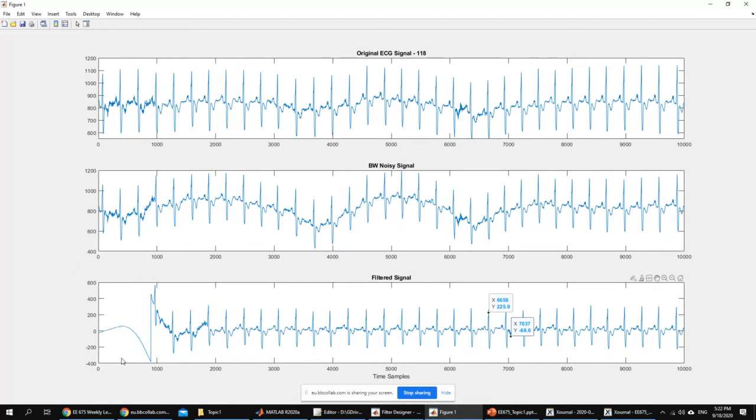So if you do it like this, you can imagine that you get the first part here from the time reversed signal and the last part here from the regular signal. Combining them together is going to give you something that doesn't have any transient and doesn't have any delay compared to the input signal that you started with.